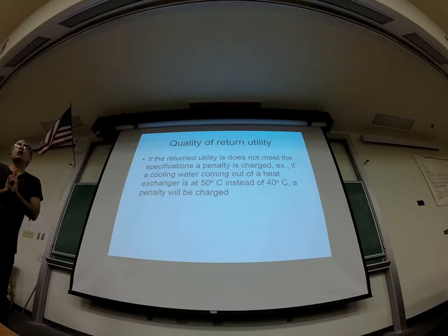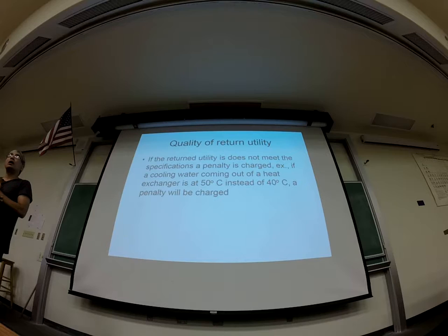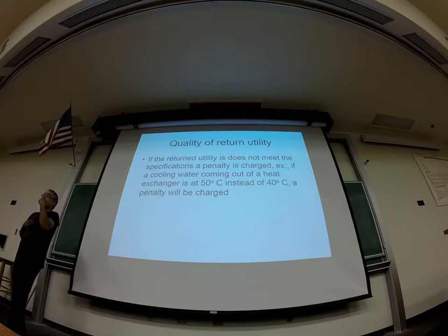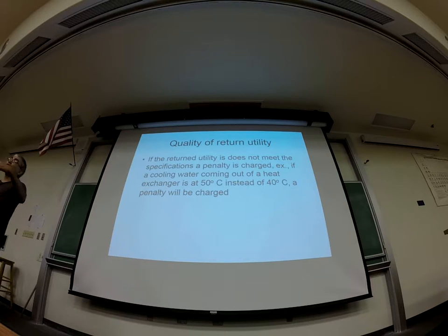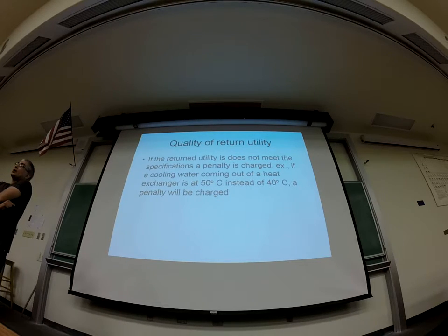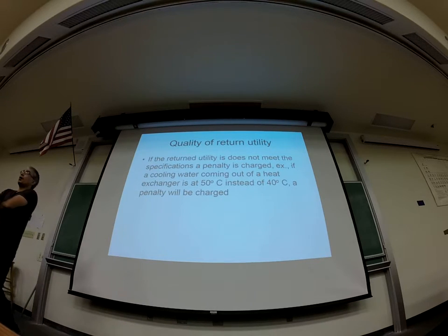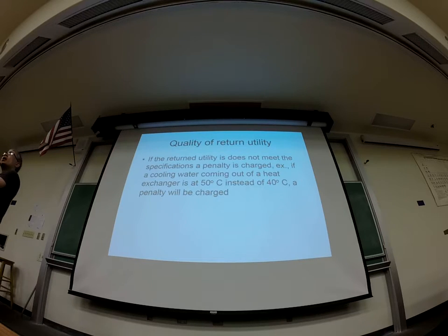Sorry? Well, the energy cost you are paying in terms of the mass flow rate, right? So the energy cost will actually go down. But sometimes the utility company may put a penalty on you. If you are using their cooling water, and you send it back to them really, really hot, they might actually charge you a penalty. Okay? Also, now this of course is not relevant if you're heating your process stream, but if you're cooling it, the corrosion rate is higher at higher temperature. So if you let your cooling water get to very high temperature, you have more corrosion.